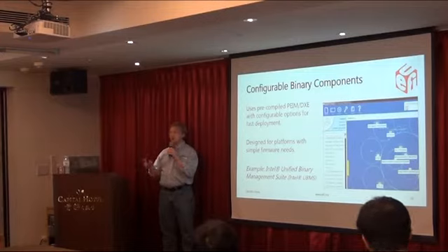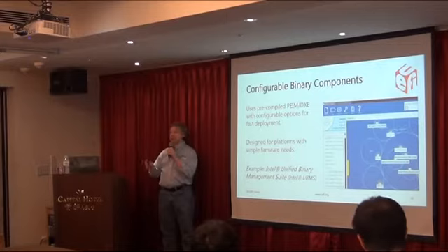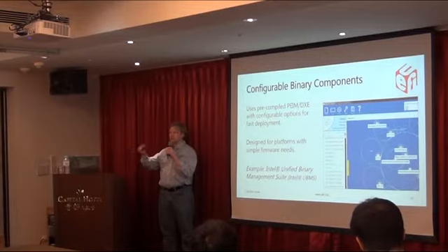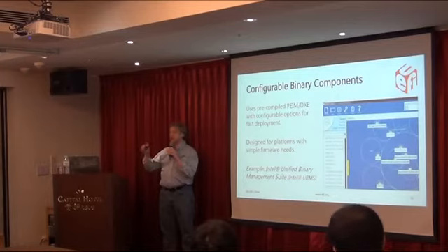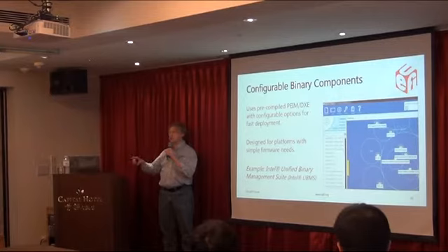So in that case, we are actually looking at a system that is still based on PEIM and DXE components, but building in some configuration options so that you could present, say, a graphical interface, and someone could say, yeah, I want to take the same thing I used for the reference, I just want to change a couple of bits here, a couple of drop-down options, reconfigure those binaries, and not build it from source, but just put those binaries together in the right piece of firmware. So the Intel example of this is called UBMS. There are, I think, equivalents for this in other architectures where there's a configurable binary that is the main distribution piece. In other words, the main thing that kicks the firmware off and gets it going can be configured through this binary option.